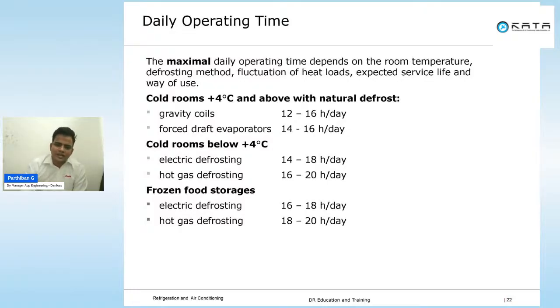If you are using electrical defrost, the pull down time considered is 14 to 18 hours per day. If you are using hot gas, then the pull down time we generally consider is 16 to 20 hours.